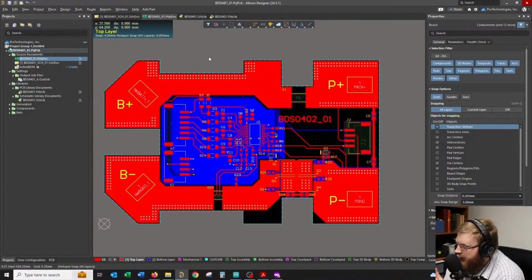But it depends on how much high current you're running, and if you're pulling more than 30 amps, you don't want anything attached or that could couple to that plane that's going to mess up your signal. So that's definitely a big thing.